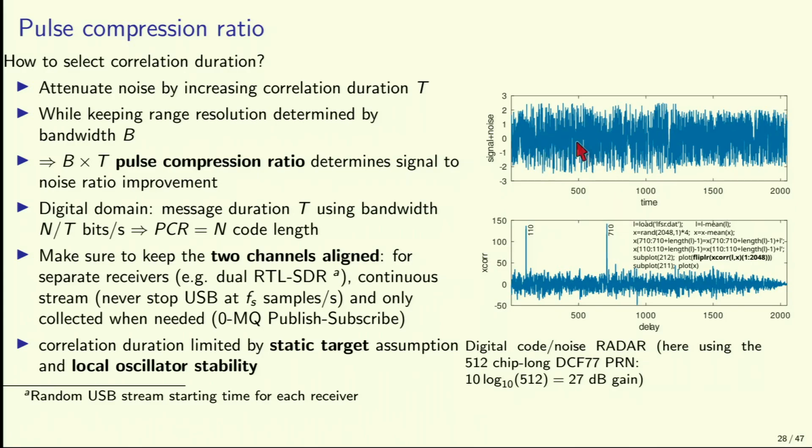This is two known copies of a signal in a noisy signal, you would be hard-pressed to detect where this broadcast code is. But by running the correlation, this is a 2048 chip long code, you see that you gain about 20 dB gain on the signal-to-noise ratio, and you can extract the signals whose width here is determined by the bandwidth, the chip rate of what you're broadcasting.